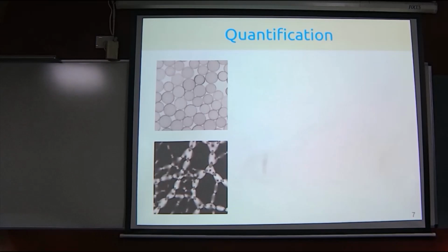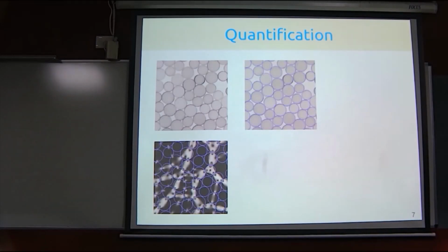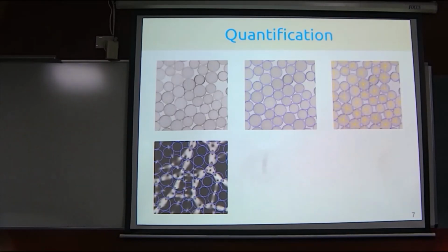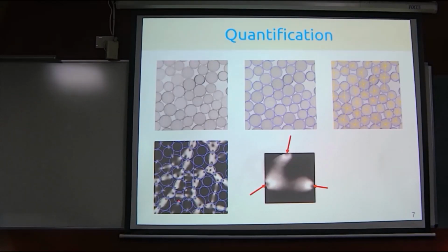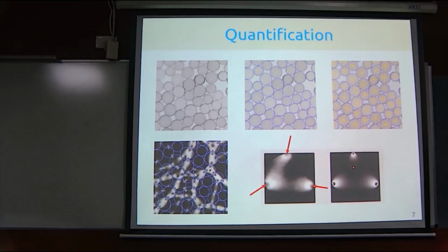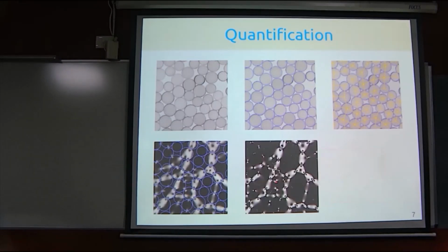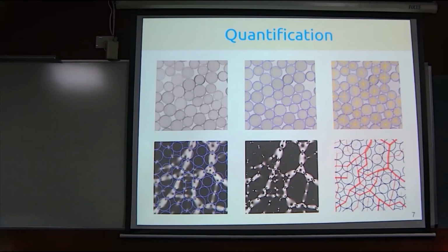From these two images in MATLAB, I have identified the particle center and the radius. And then we can say that there is some cutoff. If the periphery has a gap of about 10 pixels in diameter, we can say that there is a probable contact. Then we extract one particle at a time and optimize the three contact forces. We know that there are three possible forces from this network. So we optimize that and get a contact force. We generate a synthetic image to check that these two look similar. And now we can generate a force network similar to the DEM simulation.